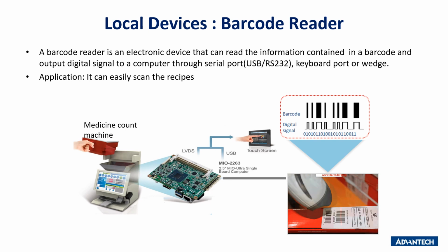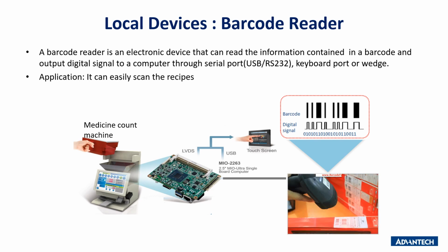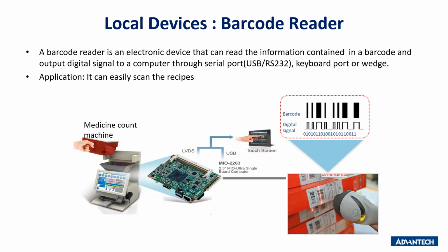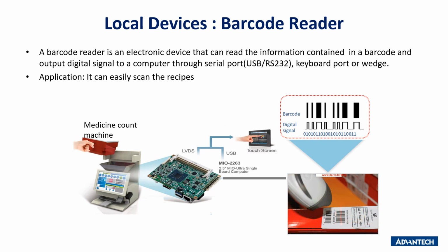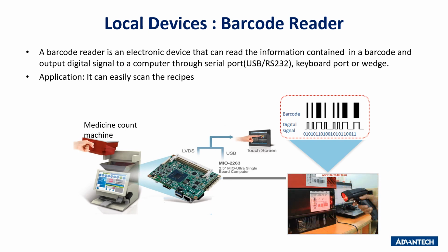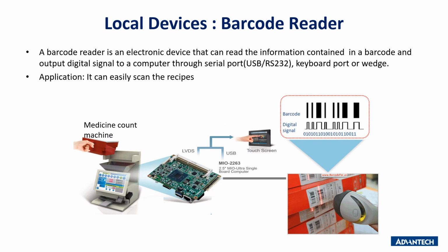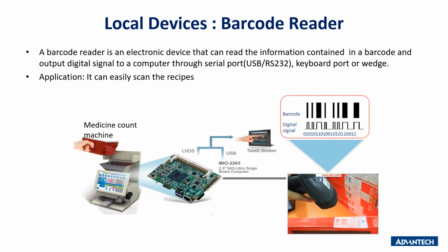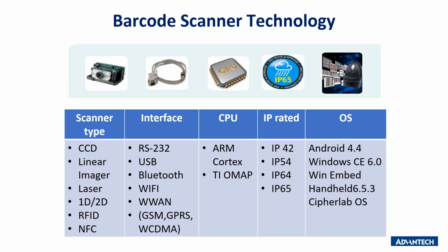When you plug in the scanner, the computer's operating system talks to the USB port to find out what was just plugged in. The barcode scanner has been pre-programmed to answer the PC that it's just another keyboard or a human interface device. When you scan a barcode, the data entry process is similar as if you just typed the characters on the keyboard. The barcode scanner has different specifications that make them very flexible to adapt to many applications.